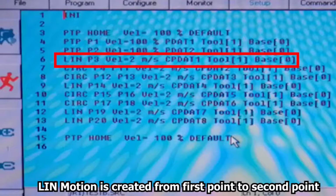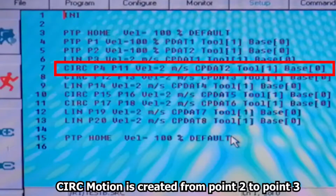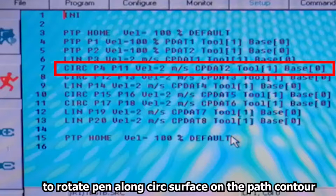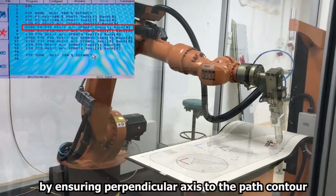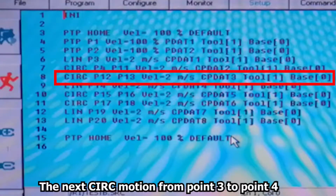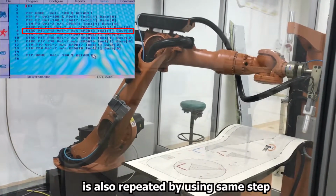After that, a LIN motion is created from first point to the second point, at speed of 2 meters per second. After the linear motion, a CIRC motion is created from point 2 to point 3 to rotate the pen along the curved surface on the path contour, by ensuring its longitudinal axis always perpendicular to the path contour. The next CIRC motion from point 3 to point 4 is also repeated by using the same step.